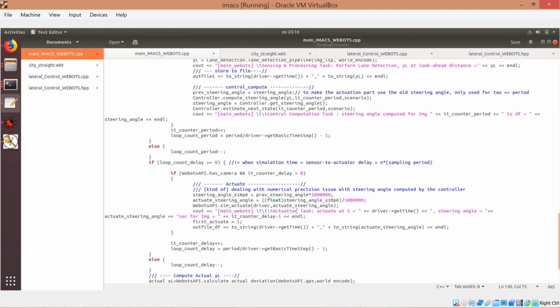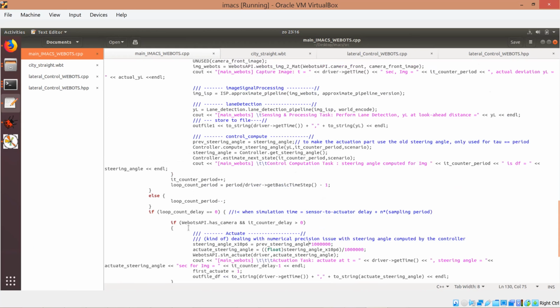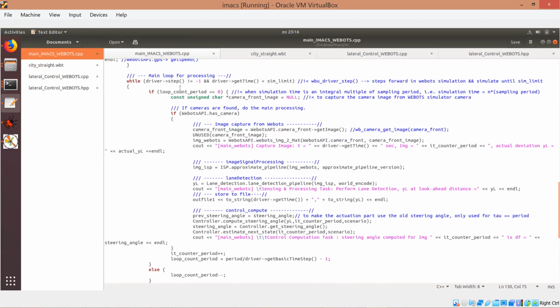But now if you have a pipeline controller, then your U is not U_{k-1}, but it would be U_{k-P} or something else. So then you need to also change this part. Essentially you need to understand how the timing progresses in this loop, and for your controller, you need to adapt that timing.